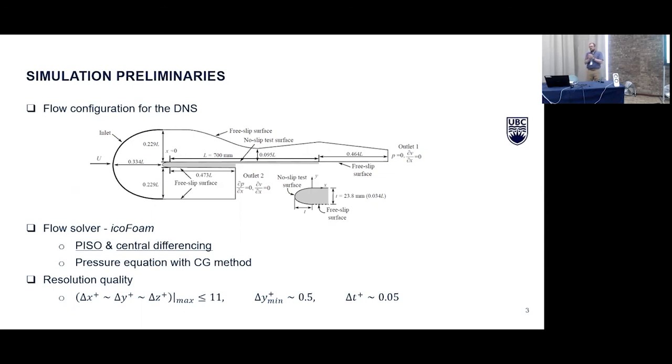If we consider the turbulence kinetic energy transport equation, we understand that pressure strain rate terms are important for the redistribution of momentum into different orientations. And so probably that would be really important here, but maybe it's not so much the pressure as it stands by itself, but the pressure strain rate correlation in the turbulence kinetic energy equation that might be more instructive. The thing about doing a DNS is you can do it and then retire and you have data to look at for the rest of your career.